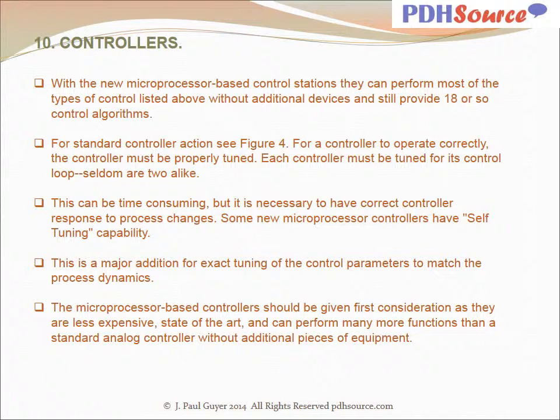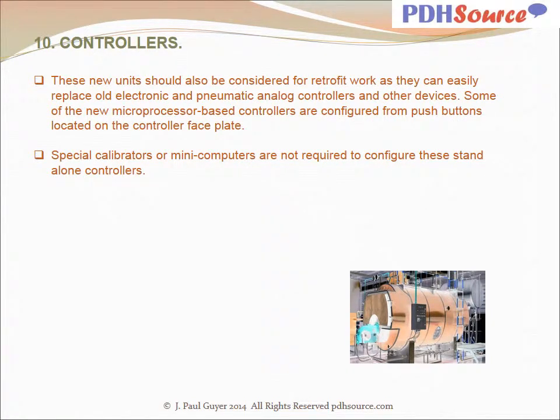The microprocessor-based controllers should be given first consideration as they are less expensive, state-of-the-art, and can perform many more functions than a standard analog controller without additional pieces of equipment. These new units should also be considered for retrofit, as they can easily replace old electronic and pneumatic analog controllers and other devices. Some of the new microprocessor-based controllers are configured from push buttons located on the controller faceplate. Special calibrators or mini-computers are not required to configure these standalone controllers.